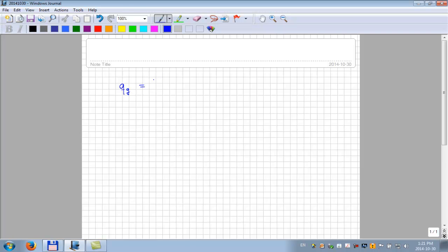And we had a constant, which I'm not going to carry through on all of this. I might come back to it for my set of units. But basically we had this KH, and then the driving potential was the pseudo pressure at average volumetric reservoir pressure minus the pseudo pressure at the bottomhole flowing conditions, like that.